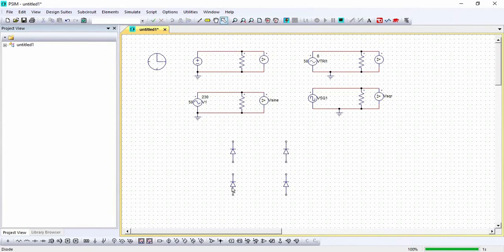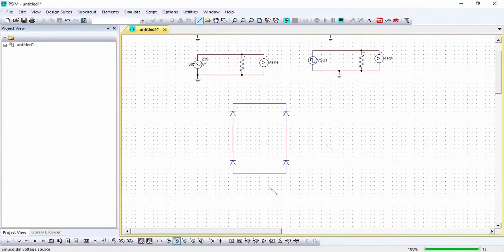Okay, for our easiness I am making some space in between that. I am taking a wire and making the connection properly. This is an unwanted part, we don't require it, so I am deleting it. Again need to connect these 2 points and the 2 ends. Here I am changing AC to DC. So we are selecting AC wave, meaning sinusoidal wave. This is our sinusoidal source. So connection is very easy.